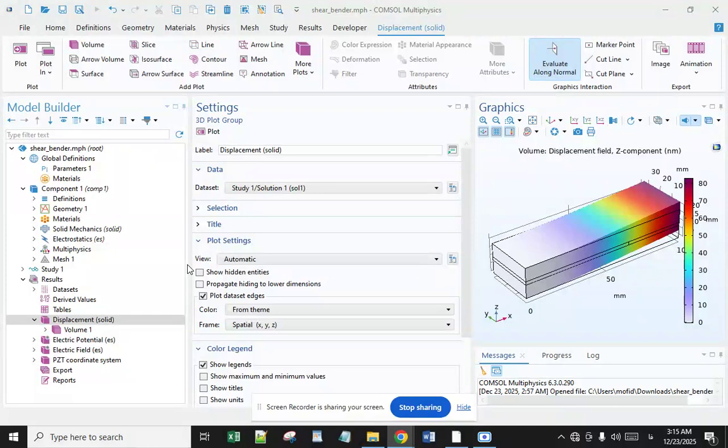A theoretical formulation and finite element implementation of a new adaptive unsymmetric sandwich beam model were presented and validated. For both extension and shear actuation mechanisms, mechanically, the model is based on Bernoulli-Euler assumptions in the phases and Timoshenko hypothesis in the core. Rotatory inertia effects were considered for all layers.